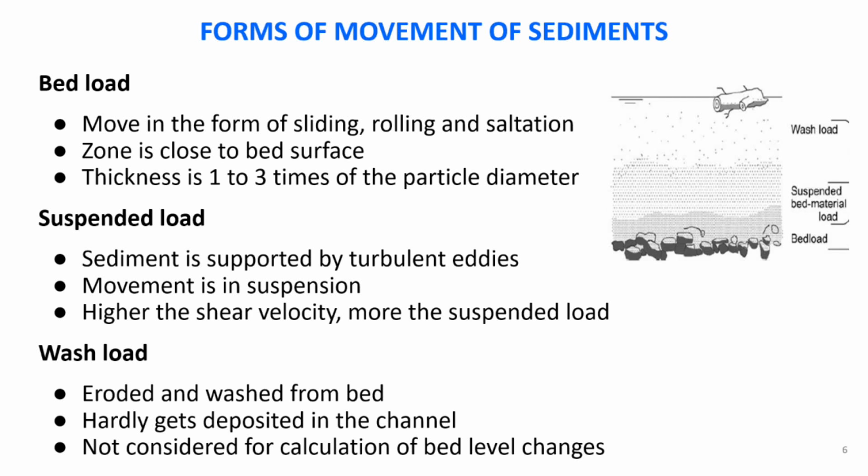Then finally, we have what is called wash load. It is eroded and washed away from the bed, hardly gets deposited in the channel, it keeps on moving. It is not considered for calculation if you want to understand the bed load and bed level changes; the wash load is not going to be of any use.